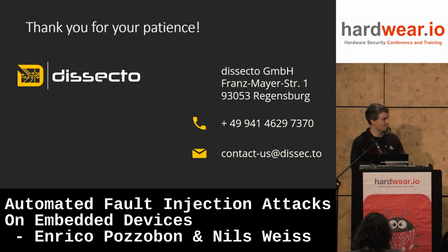Okay, and then once you could re-enable the JTAG, could you just flash down the original firmware and dump it via JTAG? Yes. Well, no, we could flash any firmware, but not the one that we erased, because we didn't have that. Basically, you had no other options for getting a firmware update from somewhere else to put back on, right? We were able to get firmware updates, but not exactly the same file that was there. From repair shop software, you can extract a lot of firmwares, but not the exact one that was running before.